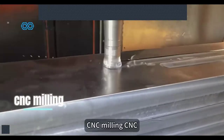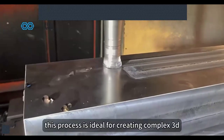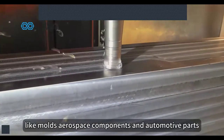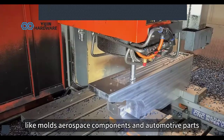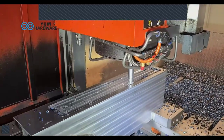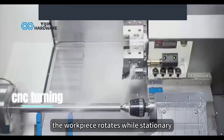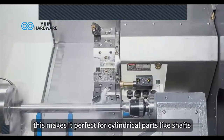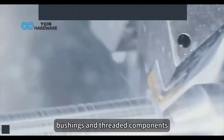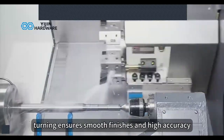CNC milling. CNC milling uses rotating cutting tools to remove material from a workpiece. This process is ideal for creating complex 3D shapes or parts with tight tolerances, like molds, aerospace components, and automotive parts. It excels in creating intricate designs that require precision. CNC turning. In CNC turning, the workpiece rotates while stationary cutting tools shape it. This makes it perfect for cylindrical parts like shafts, bushings, and threaded components. Whether you're working with metals or plastics, turning ensures smooth finishes and high accuracy.